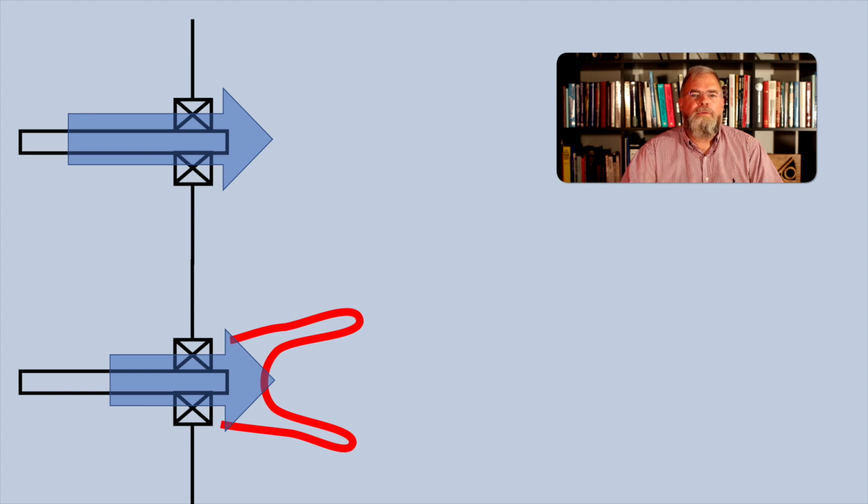Now, for simplicity in this analysis, I'm ignoring the fact that the heat release in the flame causes the flow to expand and accelerate, and this can have a significant impact on the aerodynamics downstream of the burners. This effect also produces a pressure drop, which will cause a shift in the air distribution between the burners when some burners are switched off. In other words, the air will see less resistance to flow through burners which are off and more resistance to flow through burners which are on.